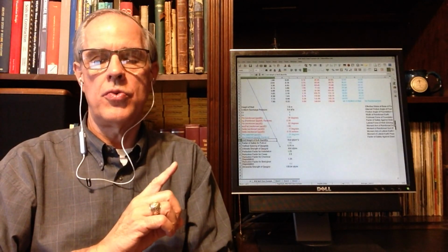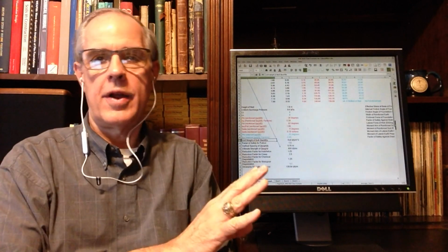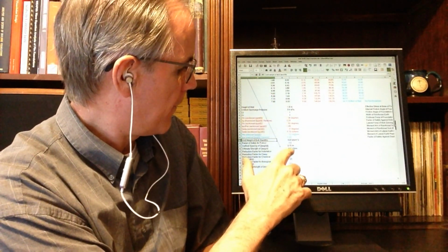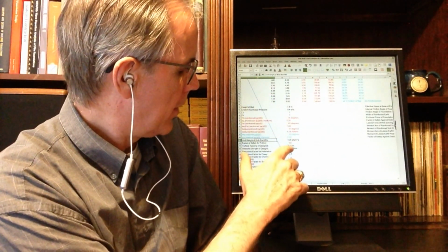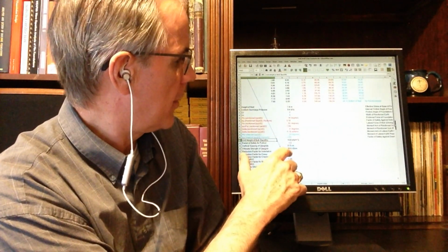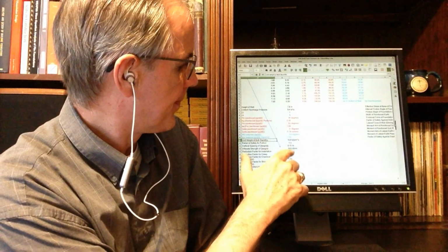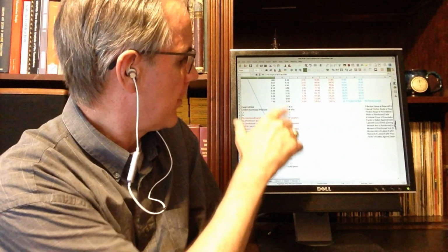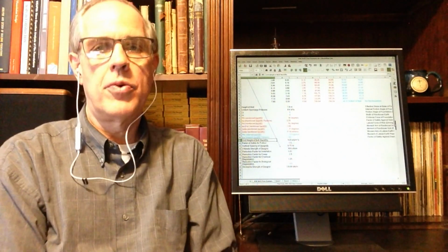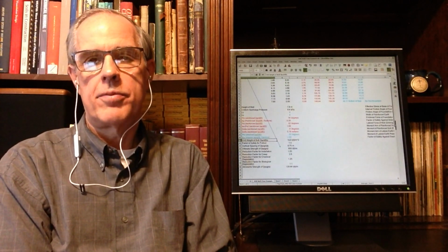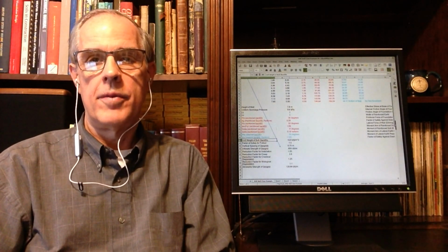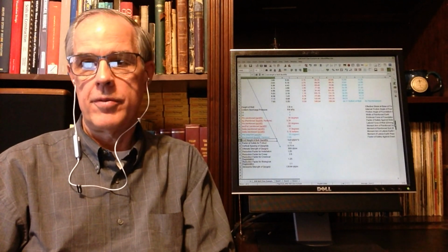In addition to what we showed on the other side of the spreadsheet, now that we're back over here, I can show you some of the basic variables. You'll see the factors that I put in here for the mechanical strength of the geogrid. We can compare that, we can get a factor of safety for that, and the various earth pressures. So it's important in any problem, again, to properly define your base variables before you get into the problem. So this is an example of how to do it with the spreadsheet.